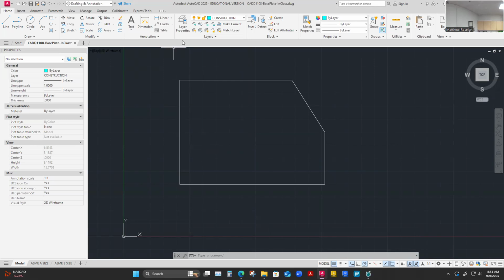So what I'll do is I'll just do the same thing with a line. I will use my polar tracking a little bit this way. I'll just pull up and say I need to go up 2.5. I haven't clicked anything. I've just locked in on the endpoint to target it and then increase values as I pull in that direction. So that's how I get up here to 2.5, but I don't really drop a line here. Like I say, you could just draw a line over it. It wouldn't be wrong. It's just my workflow is generally minimizing how many overlapping lines I have.